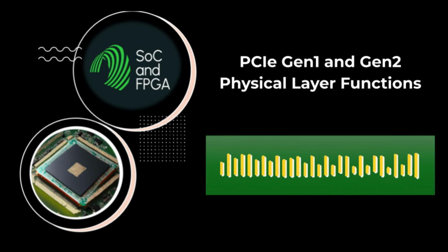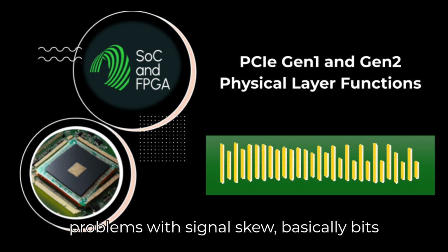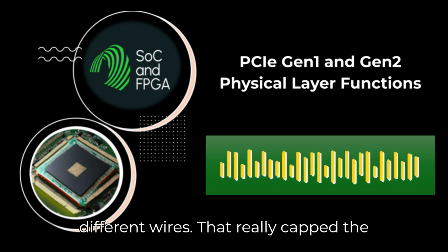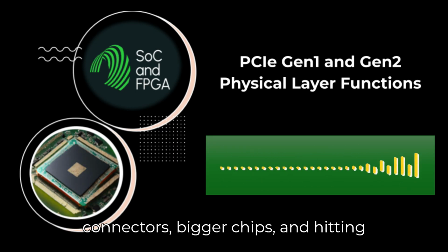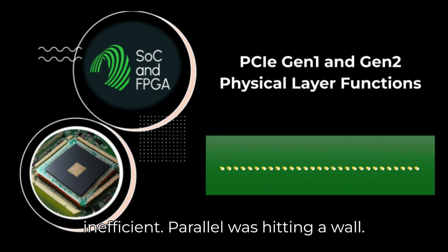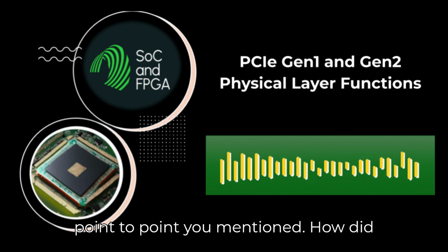Well, a few things. As speeds increased, you ran into big problems with signal skew, basically bits arriving at slightly different times on different wires. That really capped the speed. Okay, skew. Makes sense. Plus, you needed loads of pins, which meant complex connectors, bigger chips, and hitting higher bandwidths just got really inefficient. Parallel was hitting a wall. So PCIe went serial. And point-to-point, you mentioned.